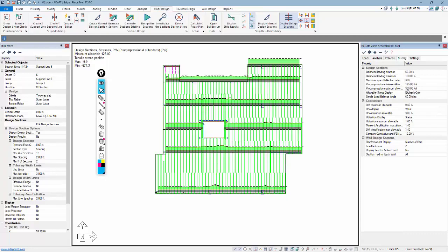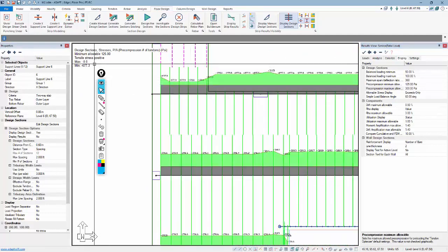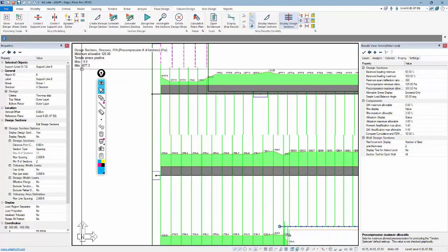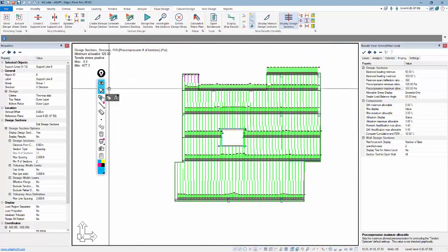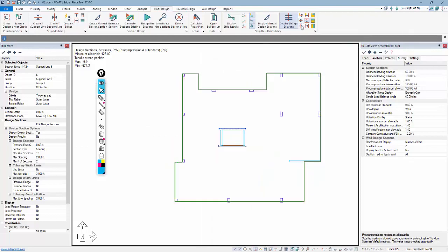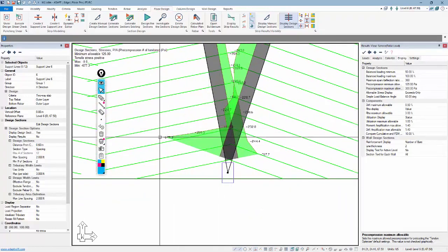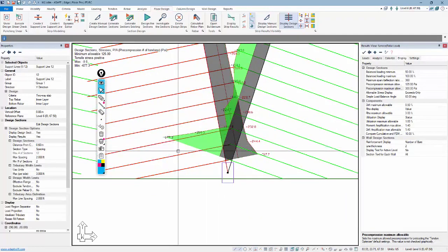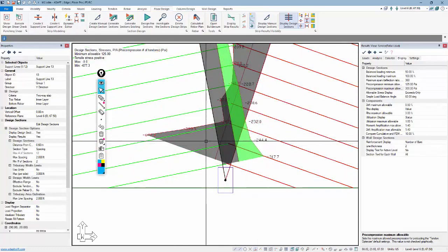Now we don't graphically code check 300, but again, the user would want to make sure you look at the maximum value. Here the maximum compression is 677. We reported it as minimum there. And we may want to know exactly where that is, because that's a pretty high value for pre-compression. So we would need to go and determine where that occurs. Well, if you see right here, there's a big spike right there. And that spike, see if we can find that.